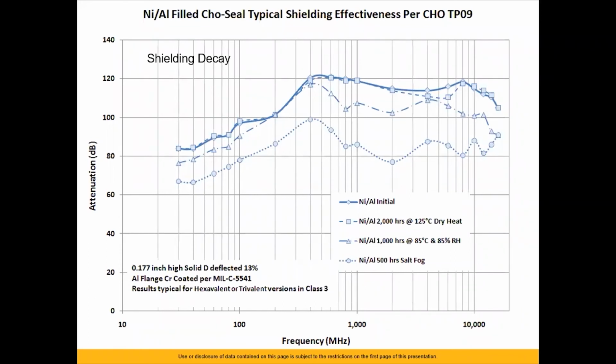So you can see the curve, actually, the shielding decays and lessens over time. So corrosion really affects your ability in the field to resist susceptibility and also not radiate its own EMI interfering with other electronics around. So it's very important to realize that, yes, you designed it perfectly, but over time, you will see some shielding decay.